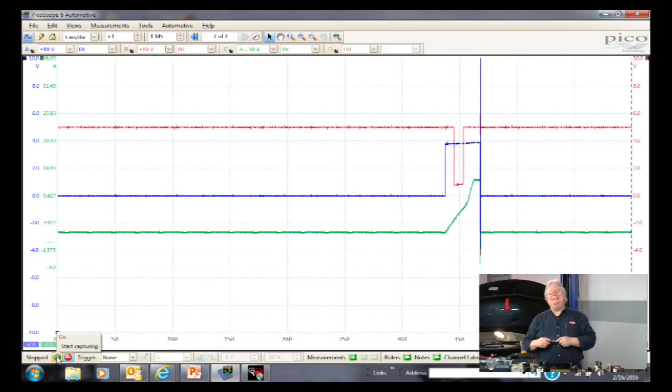So whatever was causing this problem with the code for the P0352, that problem is intermittent, and we'll have to go looking further, possibly get this coil warmed up and see if it breaks down under temperature. But for now, it's looking good.